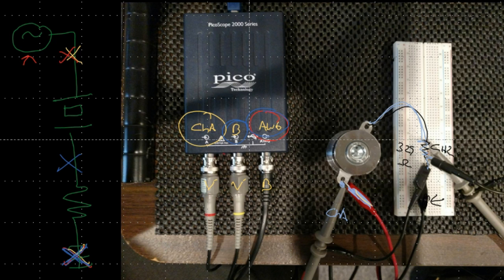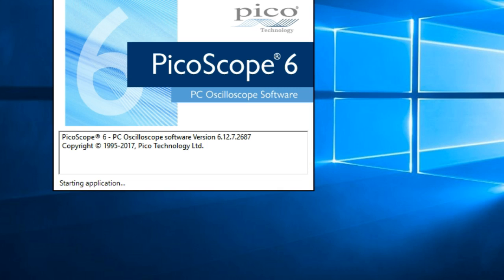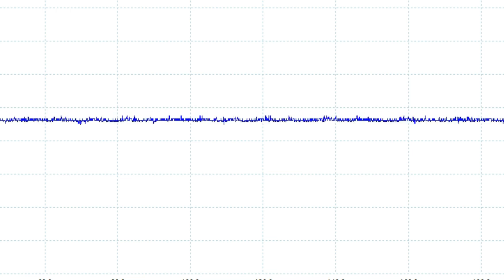So let's first set up the Picoscope. We have to measure certain properties. I mentioned you need to set up the Picoscope to make certain measurements in order for your desired measurement to come out correctly. So again, we're going to be measuring voltage, current in the form of voltage, and we're going to be computing the impedance, and we're going to be saving all of that to a CSV file.